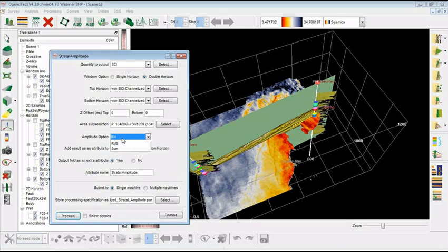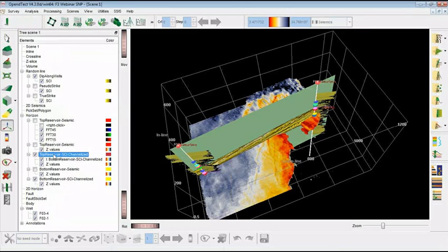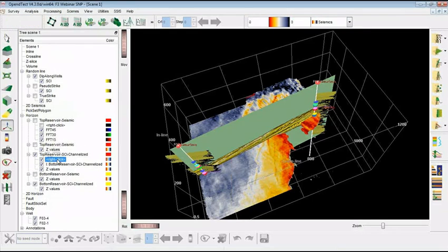And on that volume I can output different statistical quantities, and here of course I do the average. So the output would be here average seismic colored impedance reservoir, something like that. Give it a meaningful name, and then you add a result on either the top horizon or the bottom horizon here. Remember what you do. Again, I already did this, so I won't actually apply this, but I will show you the result.